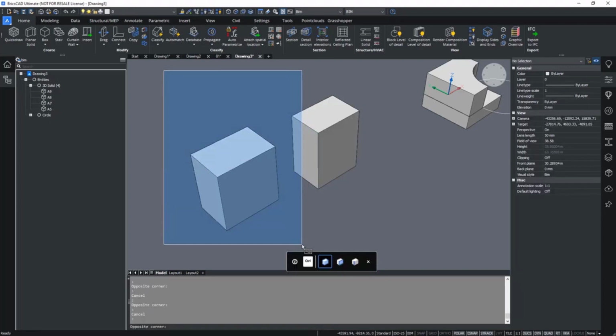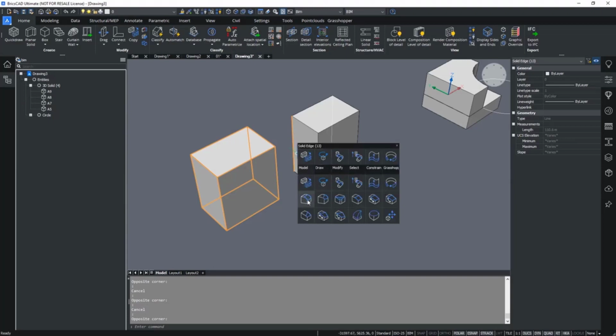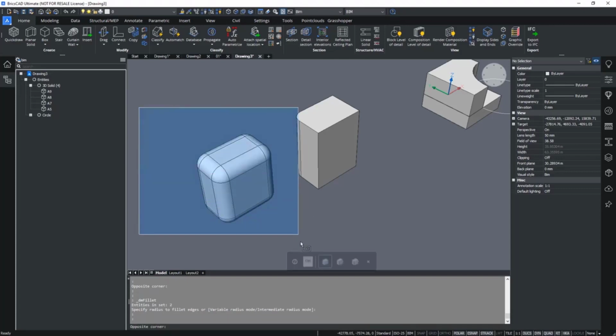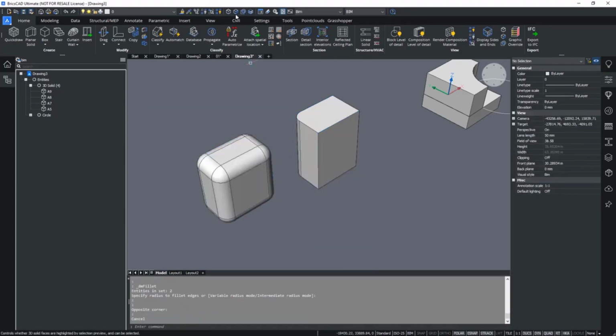And if we toggle Control 2 times, then we will have the edges selected. The edges which are inside the selection box will be selected. On these edges you can now do operations with the help of the quad, such as a fillet and so forth. So to select faces or edges, you can also use these selection boxes rather than only clicking them with the prioritized selection of faces or edges modes.